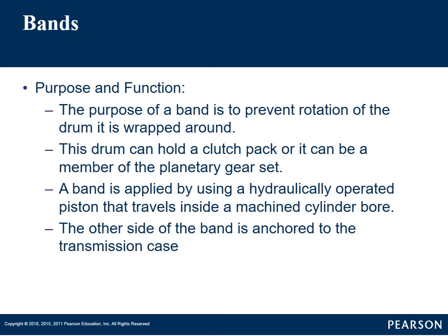So when these clutch packs and bands start to not hold, that's when we start getting slipping, improper shifts, maybe what we call sloppy shifts or soft shifts. So it's very important that these components are working properly, and it's important to understand how these components work.